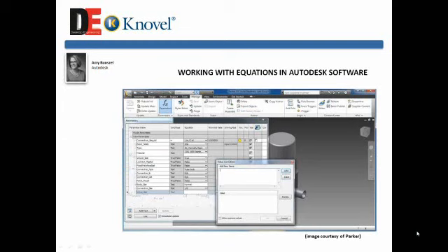Yes, absolutely. I agree with Sandy. In fact, driving dimensions from equations is a great way to take advantage of parametric modelers like Inventor and ProEngineer. You can think of it as easily as having a box and always wanting the length to be twice the width. Or if you think of a variable pattern where the spacing might change as you get further from the starting point, you can control all of this by controlling relationships.